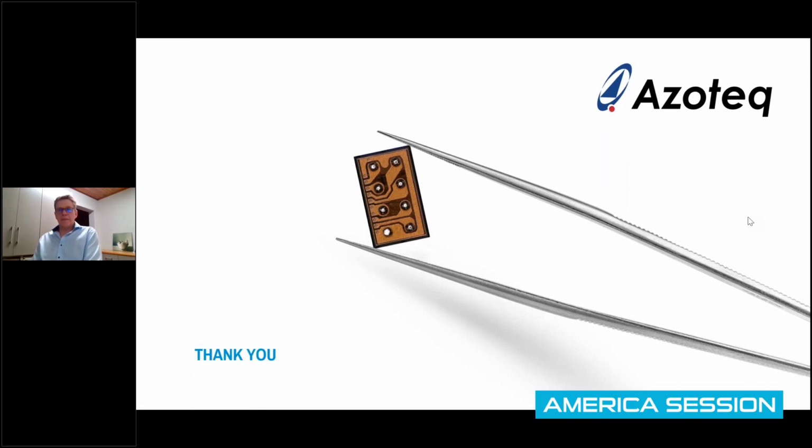Inductive sensing is based on the principle that there needs to be a small amount of movement or deflection in order to change the inductance of a coil. So you need to apply a very little bit of force. The force is a function of the stiffness of the housing, but AZOTEQ typically needs to detect 2 micrometers or more of movement.